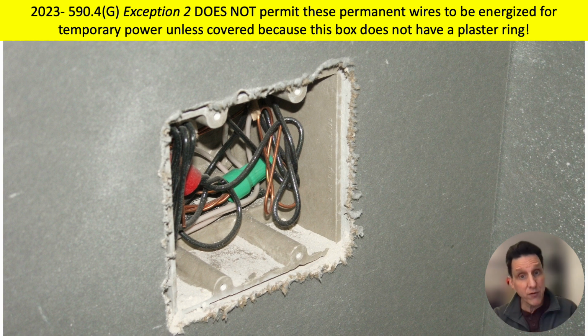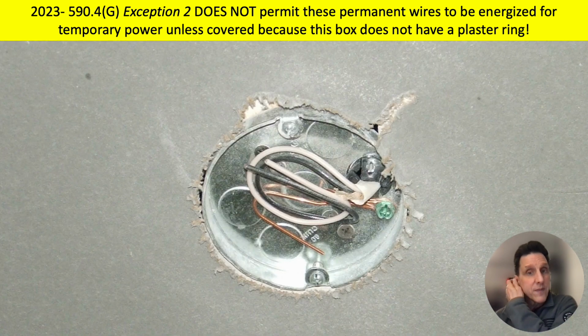Now, if you put a cover on, you could energize it, right? But if you don't want to put a cover on, they haven't painted yet, so you probably don't want the cover on, right? The covers would have to go on and off, on and off, on and off. You'd have to energize, de-energize, energize, de-energize when they're painting, for example. Here's another box, and there's no plastering on this one. So if you want to energize the wires in this box for temporary purposes, you would have to put a cover on there. And again, that's because there's no plastering.